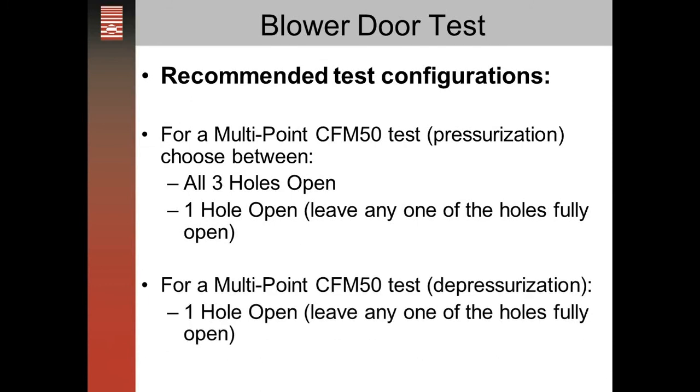If you're doing a depressurization test, it complicates things more, because now the fan is turned around and what you see from the outside from the classroom is the grate on the fan, the back side of the fan, and the flow sensor is inside the fan, and there's some turbulence associated with that, and that seems to work best with just 1 hole open.